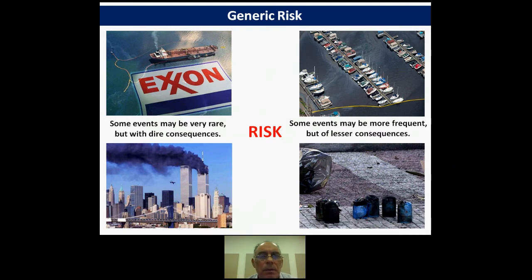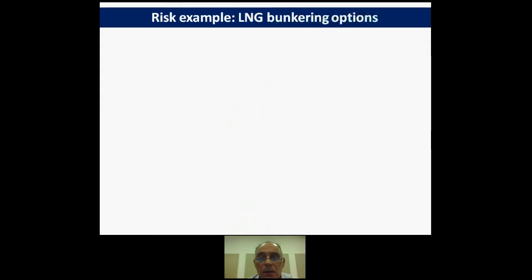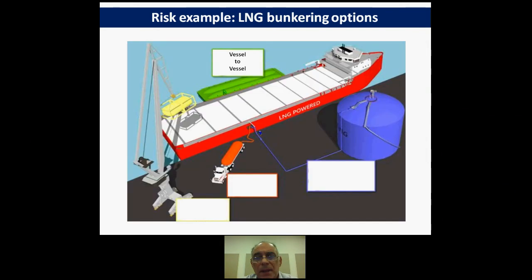With regard to LNG bunkering options, we can, for example, see that there are risks involved, whether we have a vessel-to-vessel bunkering technique or whether we're dealing with a terminal tank-to-vessel technique, or truck-to-vessel, or even a portable tank-to-vessel that involves the transfer of a portable tank to the vessel, and when the tank is empty, then we just replace the tank.